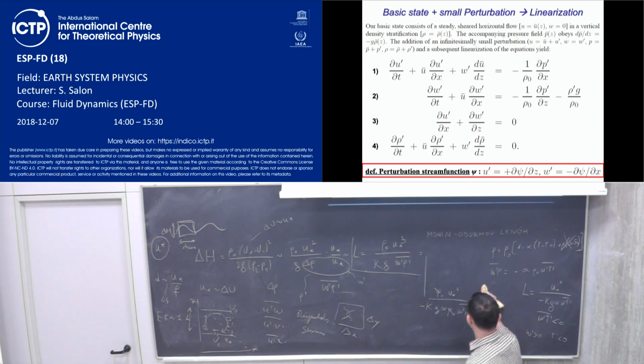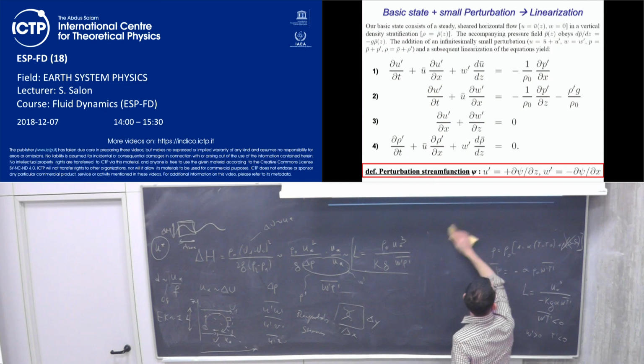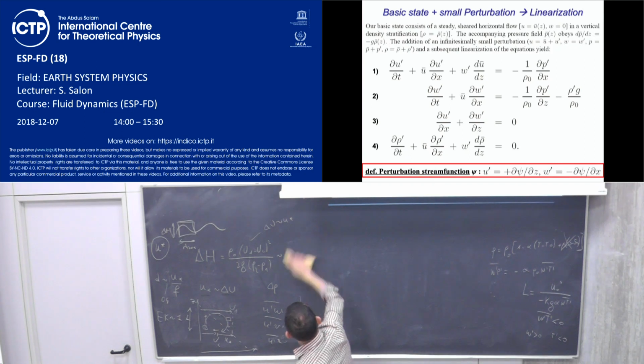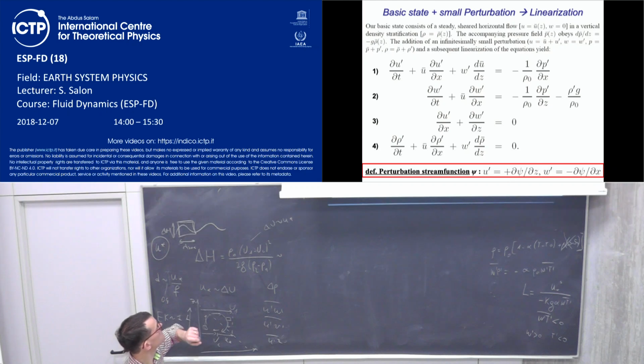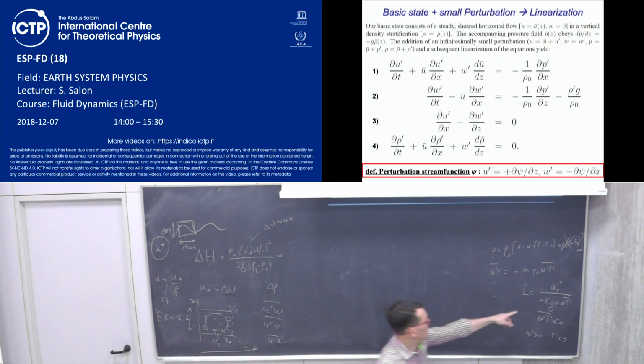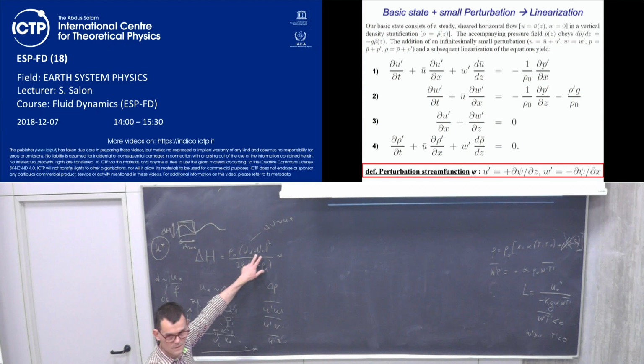Okay, so we can try to analyze some example. Excuse me, Professor. Yes. I don't quite understand what is the role of the numerator in the length scale. The denominator, we have said, is a measure of how the turbulence tends to stabilize. Yes, this one, in L. The upper is a flux of momentum, of linear momentum along the direction of the mean flow. You mean this one? Yes, the u star to the third power.